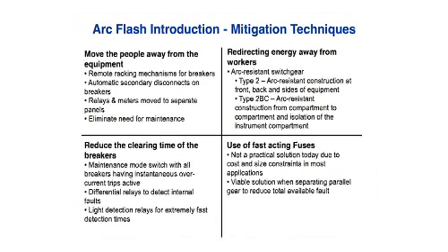If you go back in time, since the 1940s, we've always had automatic secondary disconnects. And we created, in effect, the test position. So all switchgear today, you have a disconnect position, you have a test position, you have a connected position. In the IEC world, you only have connected or disconnected, and you have a plug that creates the test. Doesn't say it's wrong, it just says it's different.